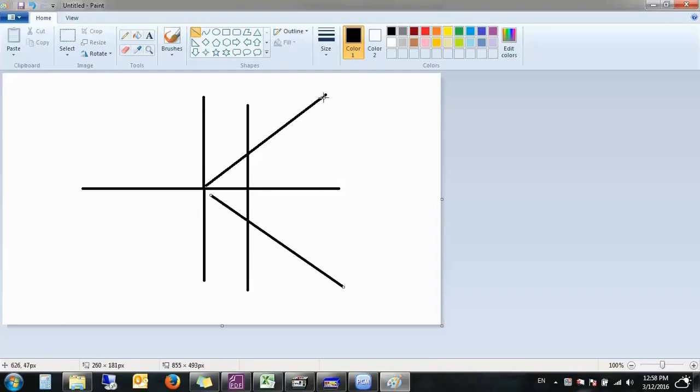At that time, this area here is outside. Even if there was a zone in this area, it doesn't belong to these zones. We call it load blinder or load encroachment. In the microcontroller, it gives you another option, saying, how would I know? I might have come here due to a fault. Who said it's a load blinder? It will tell you no problem at all.